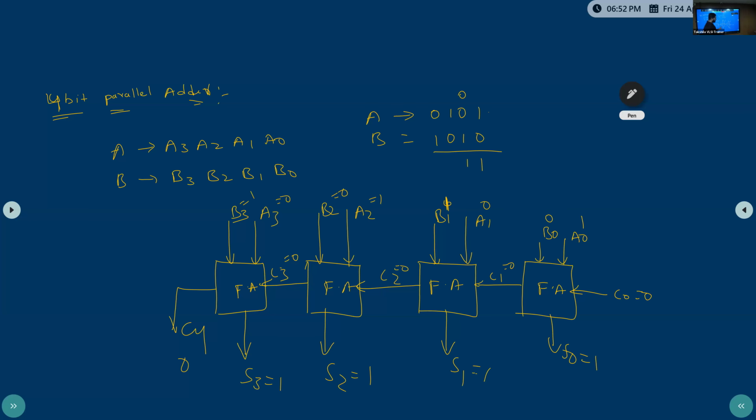So now see, this is added, and based on that addition a carry is generated or not. As the number of bits keeps increasing, the delay keeps adding. Suppose one full adder takes 5 nanoseconds for carry generation. Then 4 full adders take 20 nanoseconds to complete the task. As the number of processing bits increases, the delay also increases.